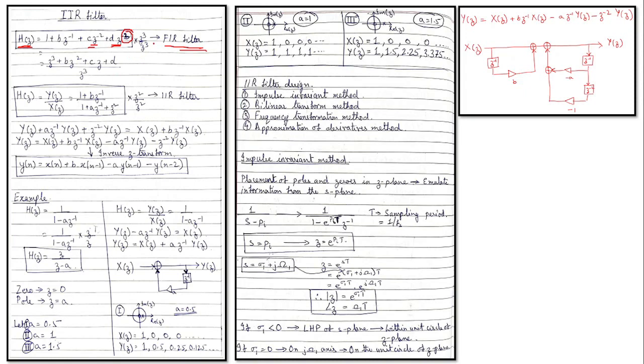So by doing so, we get such an equation, and we get two polynomials, and if we solve the numerator, the roots of the numerator will give us the positions of the zeros, and if we equate the denominator, then we will get the positions of the poles. Okay.